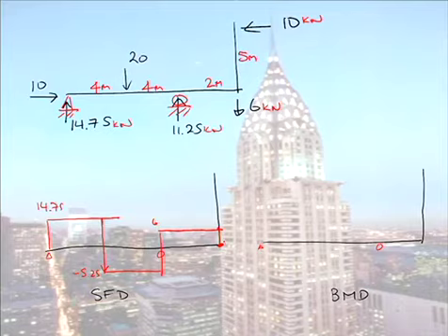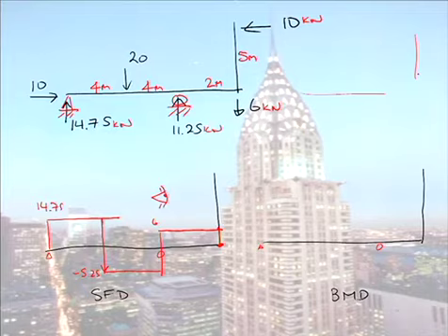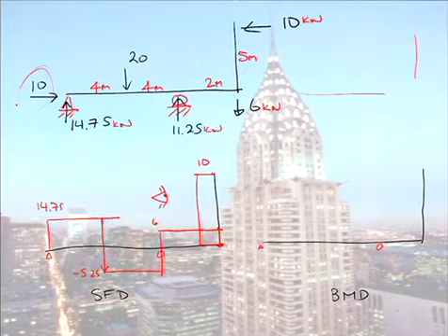Now when we come and do the vertical leg, we can look either way. It doesn't matter. As I said, we'll look at it from the left this time. Some people get confused and they want these separated out. If you want to draw them separated out, you can, but I will just draw it as one now. We are looking from the left, so we step down a value of 10 because the left side now is the top of our cantilever. We step down and then we step up because, of course, that step up comes from that horizontal reaction. So there's my shear force diagram.